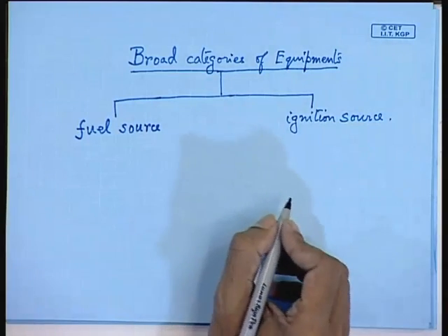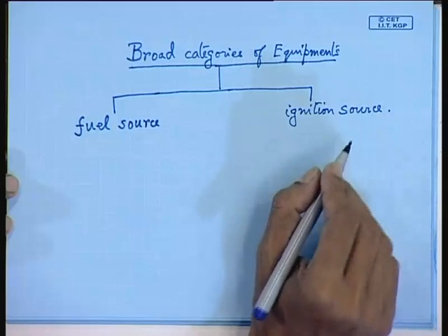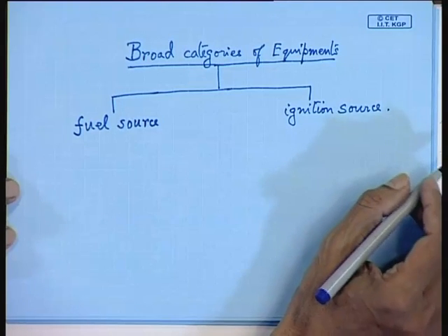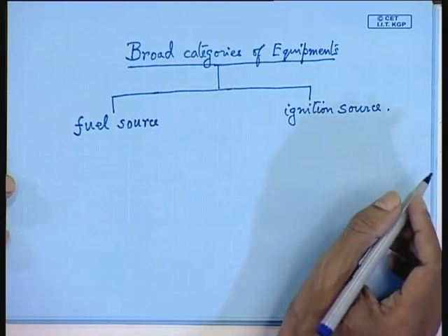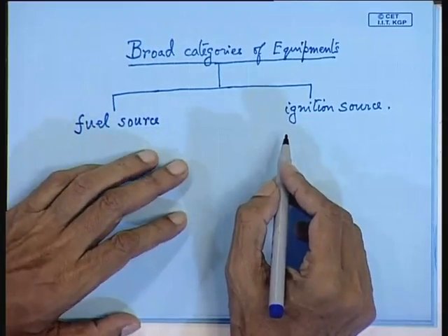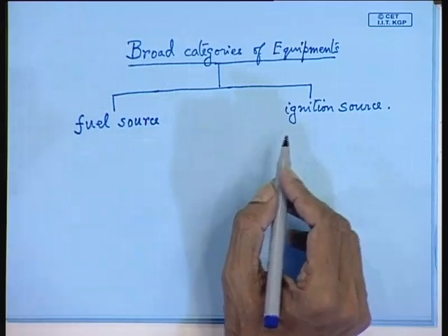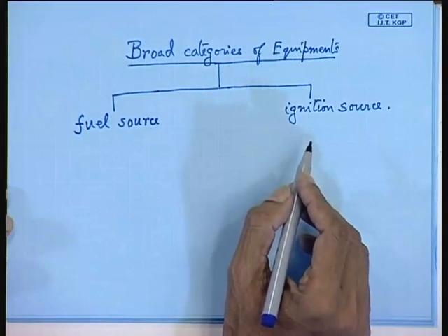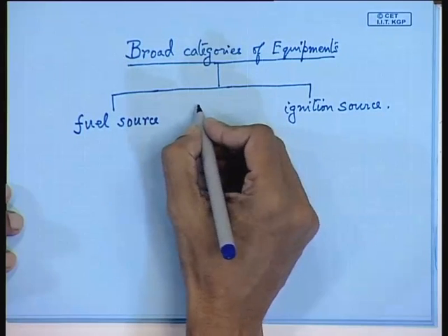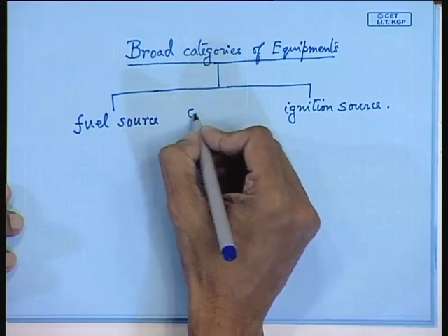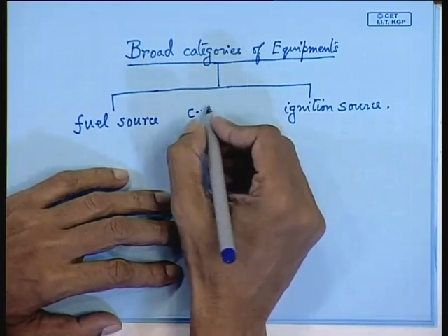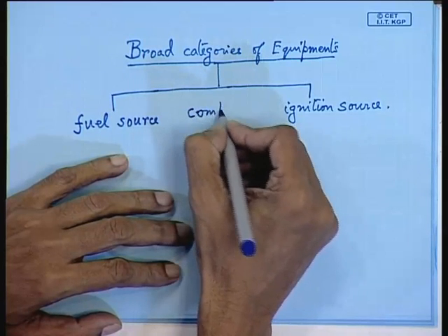So, now remember this, all your topside layouts are going to be inspected by your surveyors. So, that means you have to satisfy the surveyor requirements, and it may not be possible to segregate completely fuel source with ignition source, because of the constraint of space requirement. So, you have to strike a compromise between these two somewhere. Now, there is a trade off actually. So, the risk of fire is there. So, that is one of the most disastrous consequences. So, you have to strike a compromise between these two.